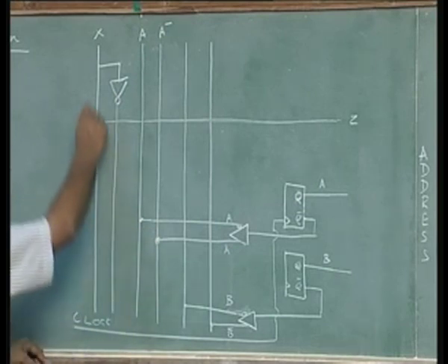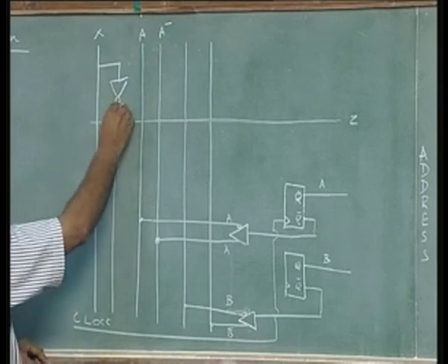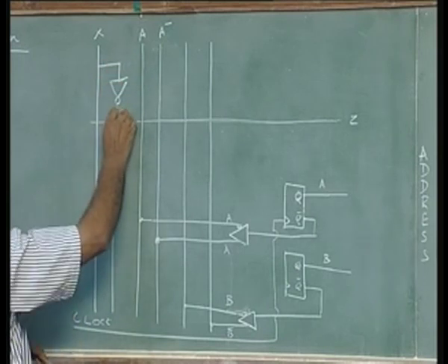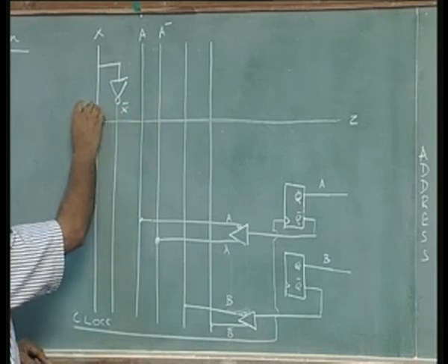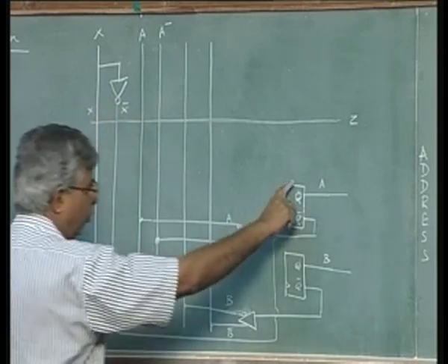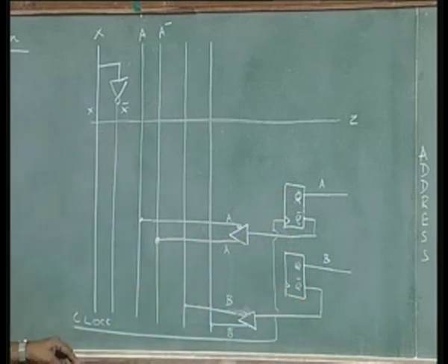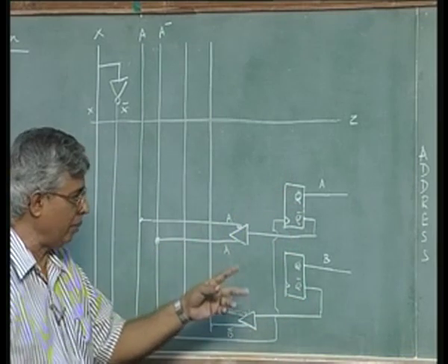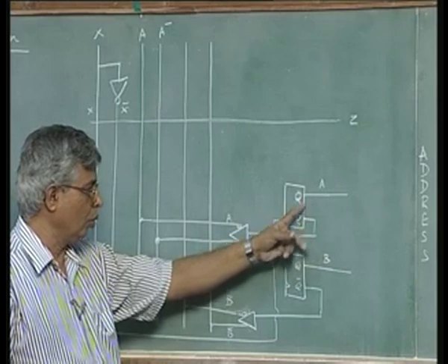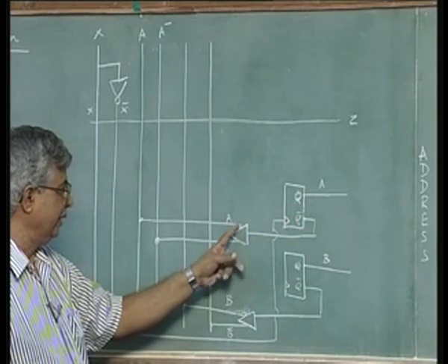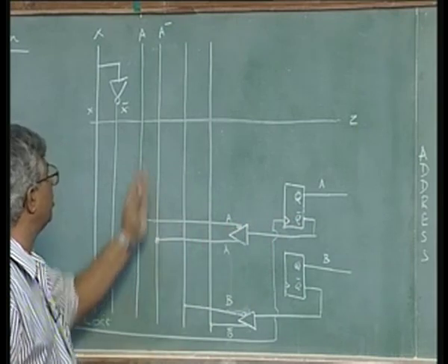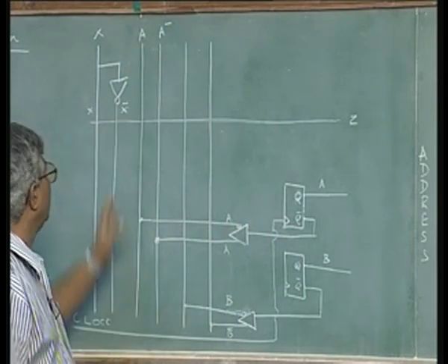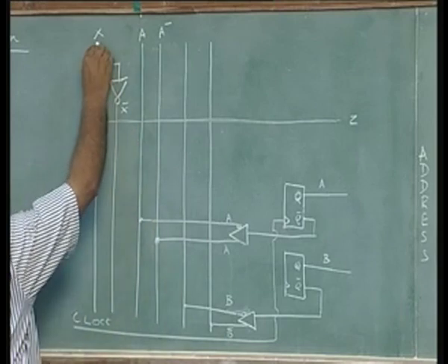So we have this X given to this, and X bar, of course. This is X bar. I have two flip flops. There are many registers in the output. I am going to choose two of them. One of them, Q and Q bar, is fed back. This becomes A bar, so I put an inverter, so A and A bar. So this also acts as an input to the combination logic. So these are all the inputs to the combination logic, X, A, B.